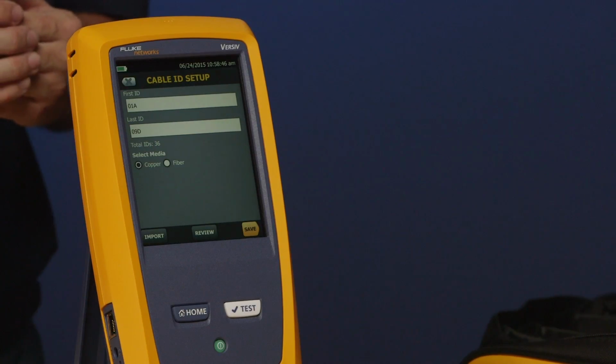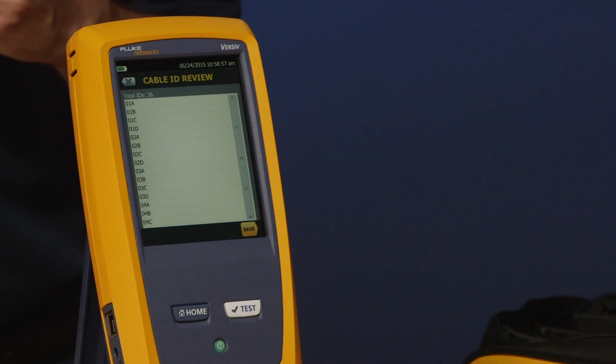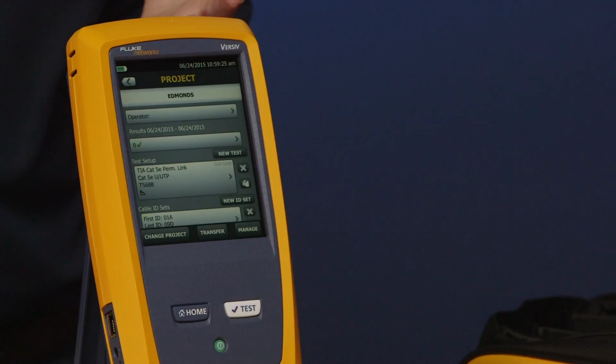Okay, go ahead and tap the review button for me, Amanda, please. So here you can actually review your cable ID scheme. And what you'll notice is, once I get to 01D, it doesn't jump to 01E. Because you told it the last digit is a D, it's smart enough to figure that out. Now this is very useful if you're doing an installation with quad faceplates, for instance, or you're doing a fiber optic installation where every ID is alternating between A and B. This is a way of really improving your work efficiency. So we're good with this, so go ahead and tap save. That's our setup configuration done.